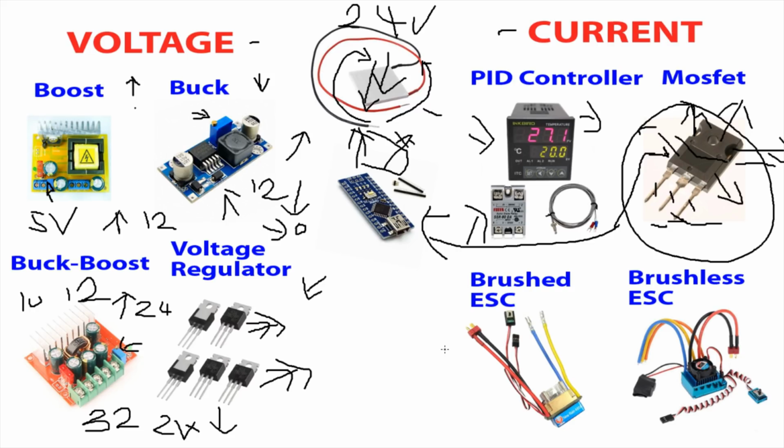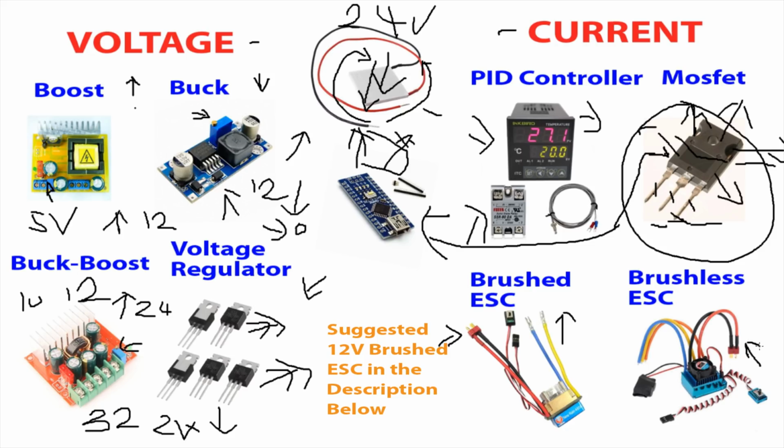If you're using a brushed speed controller, which is for old school motors, the answer is yes. And you could say this is the most successful way of controlling a TEC's voltage, because they're an all-in-one solution. They're built for huge amps, so use one of those. So a brushed speed controller has 2 inputs and 2 outputs. This is the power in, goes to your battery, and this is the voltage / power out. Now on a brushless speed controller, you have power in, which is 2 wires, and power out, which is 3 wires.